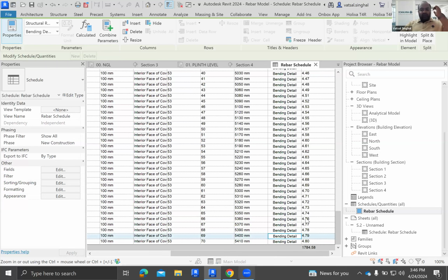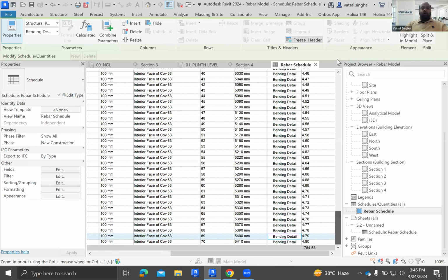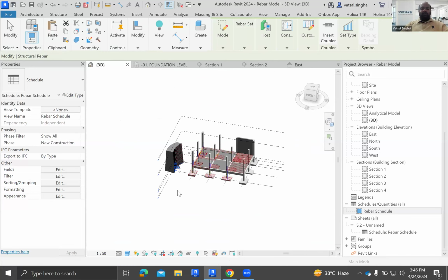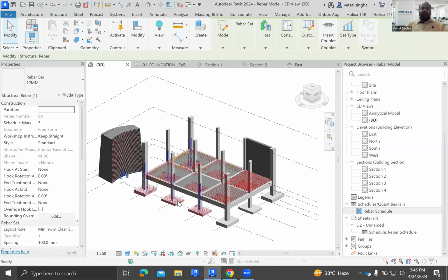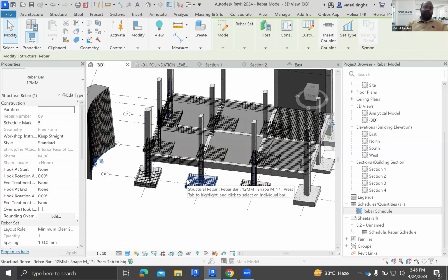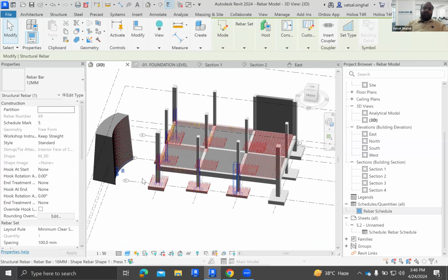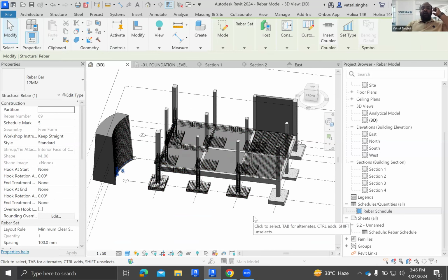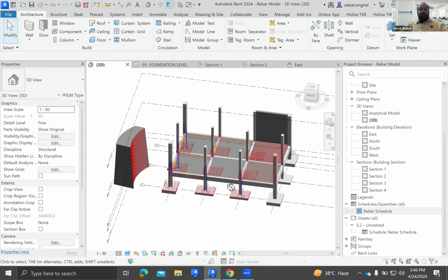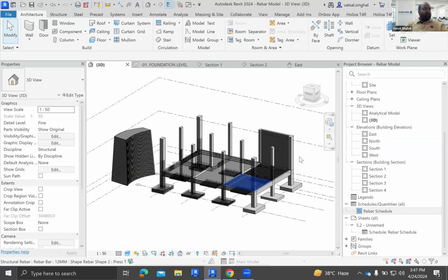So this is actually in kgs only. That is the amount of rebar that we have used in this small model. So this is a very small model, so you can also accurately check. I have used this actually on site, so it is very accurate. The total bar weight, you obviously have to calculate 10% wastage and the other things also, because this wouldn't calculate the wastage part. This will tell you the exact weight that is there, but on site there's a lot of wastage, so you also need to calculate that with this, right? So that is it from my end.